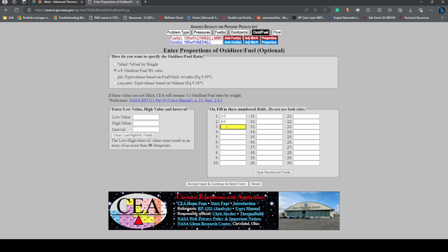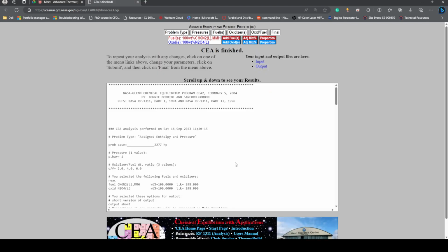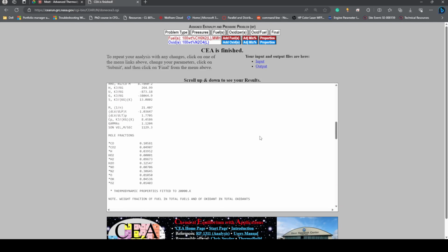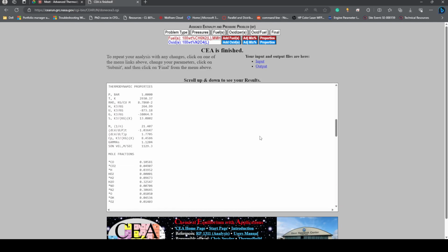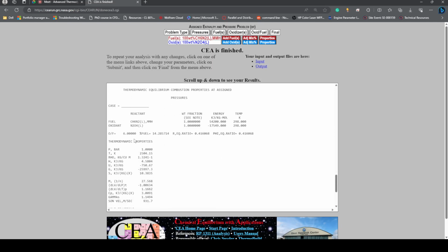It is helpful in terms of design, and also in terms of economy when you have a gas turbine engine, because you cannot keep on spending an amount on fuel. If you spend an amount on fuel, prices will rise, right? So this is for oxidizer ratio 2, and if you scroll down, oxidizer ratio 4, you have 2700, and if you keep scrolling down, for oxidizer ratio 6, you have 2500.